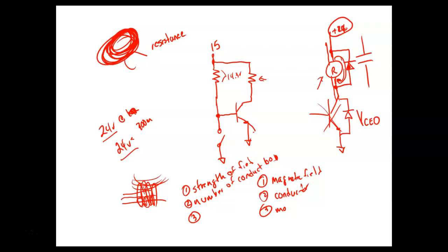Well, there's no way in the world those lights out there that are pulling 5 or 6 amps are coming up to that little tiny switch on your steering wheel or on your dash. So what are you doing? Well, you're saturating a transistor out there. The transistor's turning on a relay, and then the relay's running your light. So you're seeing saturated switches all the time.